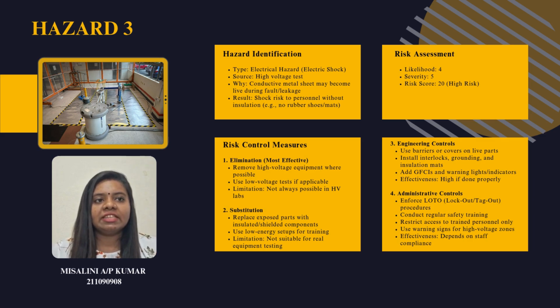I will now present hazard 3, which involves the risk of electric shock during the high voltage testing. The source of this hazard is the conductive metal sheet used in this test area. If a fault or leakage occurs and the sheet becomes alive, anyone stepping on it without proper insulation could suffer a fatal shock. The risk assessment shows a high risk of 20.